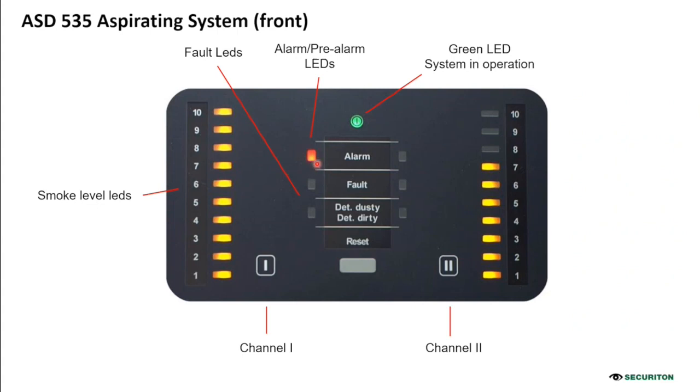Then we have an alarm LED, one per channel, and indication of faults. So there could be a general fault, or a detector dusty or detector dirty fault.